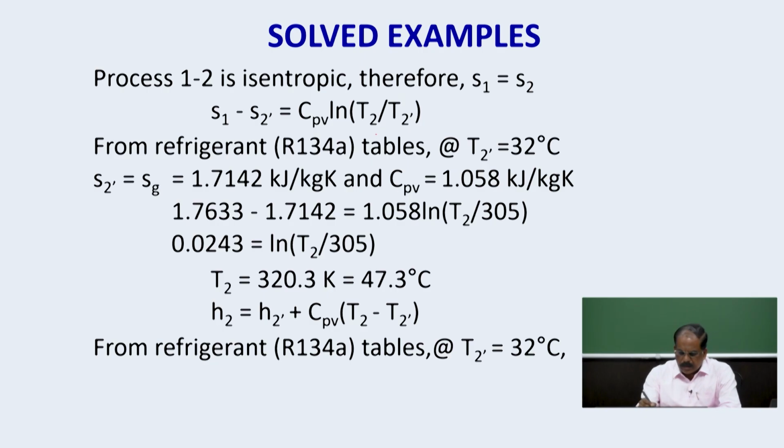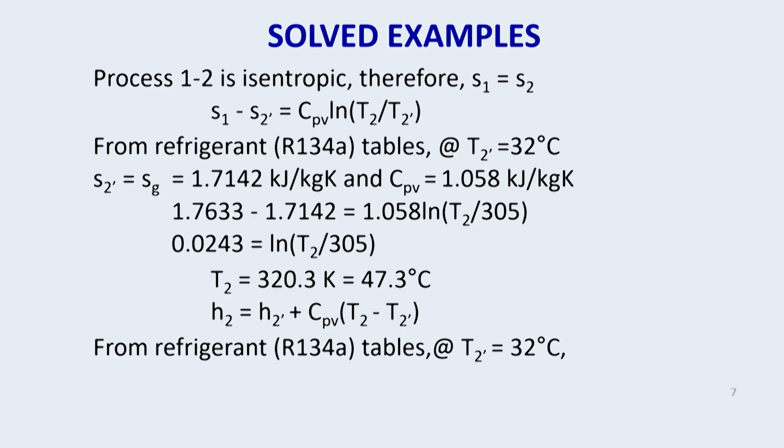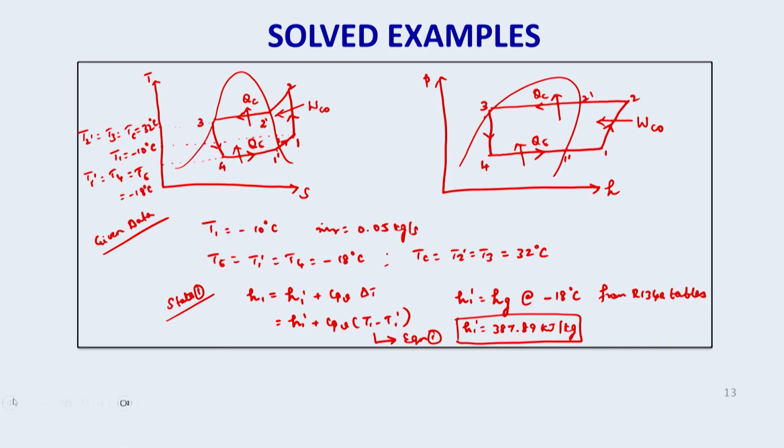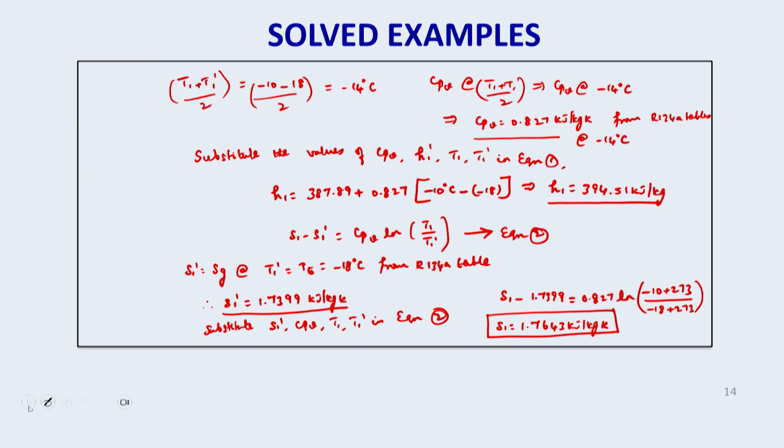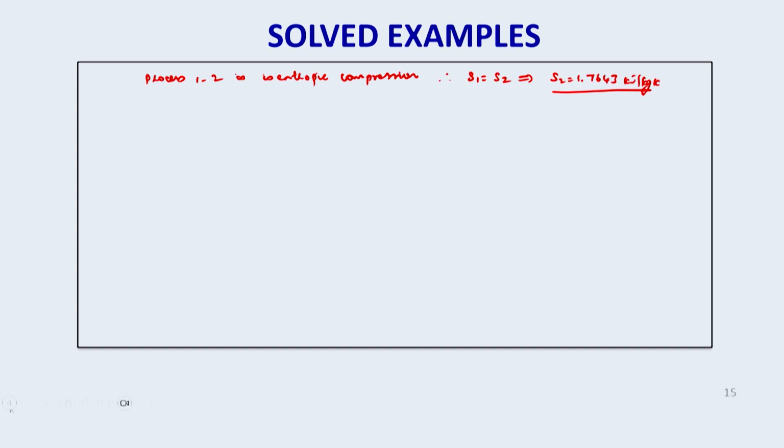we can use the formula which we used, because we don't know the temperature of the refrigerant vapor after the refrigerant is compressed. So here, this temperature is unknown. We don't know the T2 temperature. So this temperature needs to be found out. The temperature at superheated condition 2 is not known. I will be using an equation similar to this equation to find out the temperature T2.